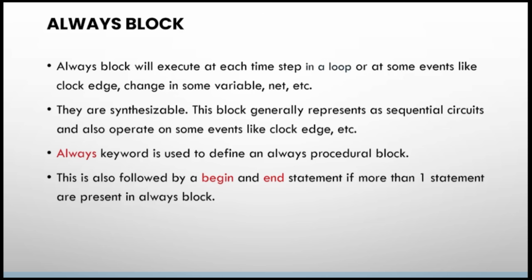Just like the initial procedural block uses the initial keyword, the always procedural block uses the always keyword. When it comes to similarities, in both initial and always blocks, if you have multiple statements, you will be writing them within begin and end.